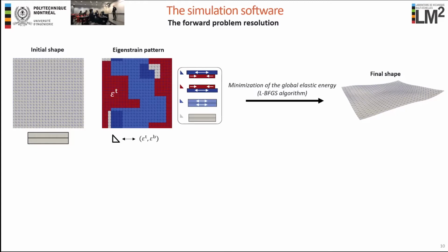In fact, this general approach of loading the component with a non-elastic strain assigned to its structure is called the eigenstrain approach. And this non-elastic strain is the eigenstrain. So in our case, epsilon top and epsilon bottom fit the definition of eigenstrains. So we'll load the component element-wise with these eigenstrains, and in this way, we can actually draw many different peening patterns. For example, as we see here, we see 4 local load cases in this pattern.